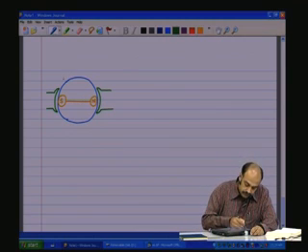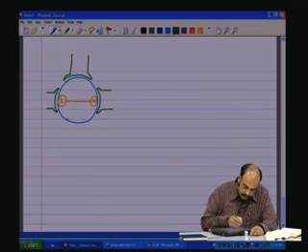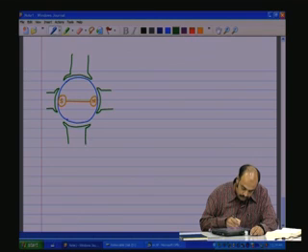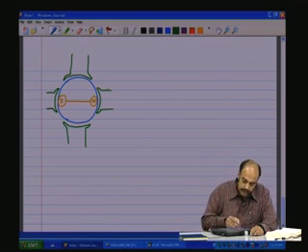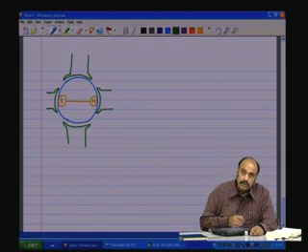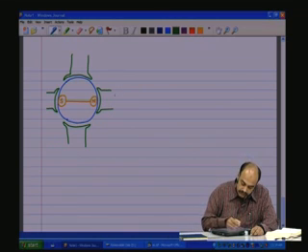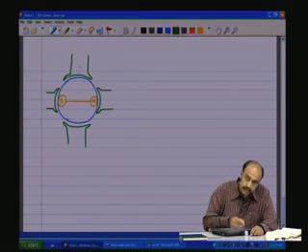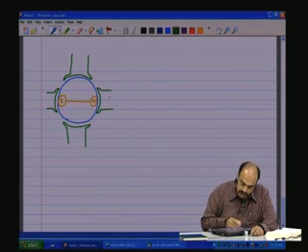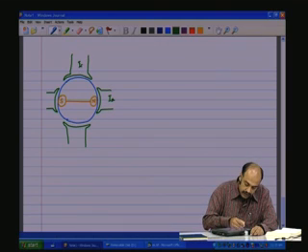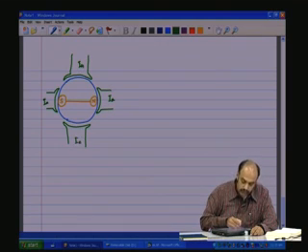Now let me have two more poles in the A phase, all A phase, and the windings are done such that the north and south poles alternate. All the currents flowing through this, and then this, and then this, and then this, they are all IA, and IA is flowing through all these four.